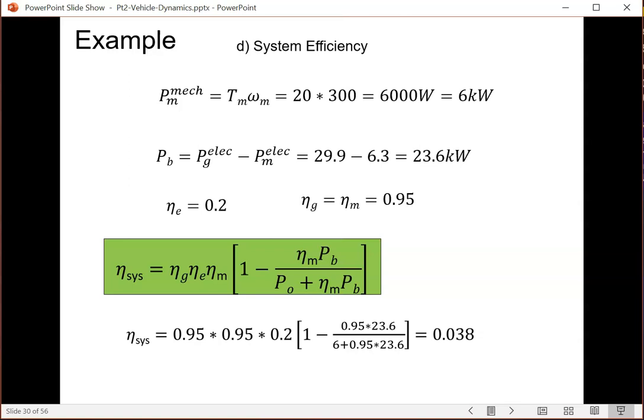So the best you could get, if everything else works perfectly, is 0.2. That's partly why conventional series hybrid vehicles have their own limits, because the efficiency of the engine can never be any good. The other factor is that a lot of energy is used to charge the battery. So the energy is actually stored, it's not lost.